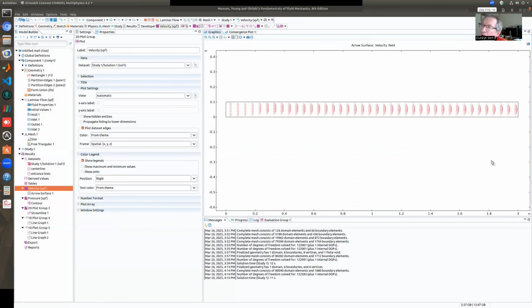Another thing is a converged solution does not necessarily mean a correct solution. So a solution may converge, but it may converge to something wrong, maybe due to your poor mesh, improper mesh, maybe due to your other settings, right? So maybe the flow is turbulent and you're solving it as laminar. Maybe it is unsteady, but you're solving it as steady, this and that. So there can be lots of modeling issues and problems.